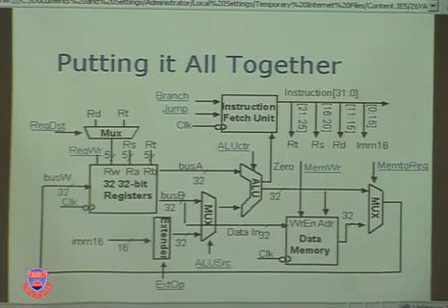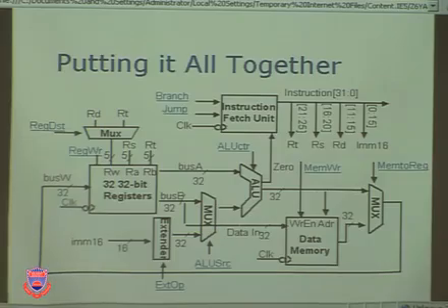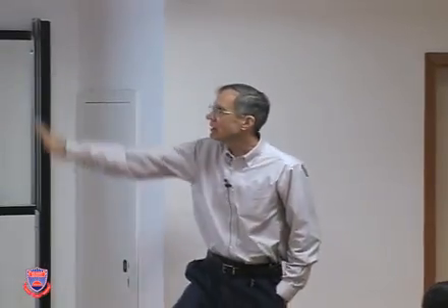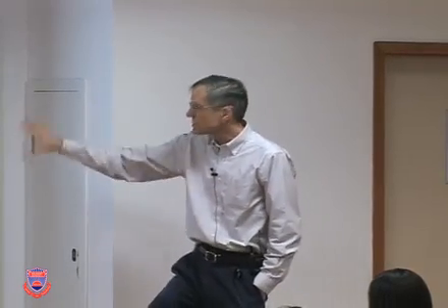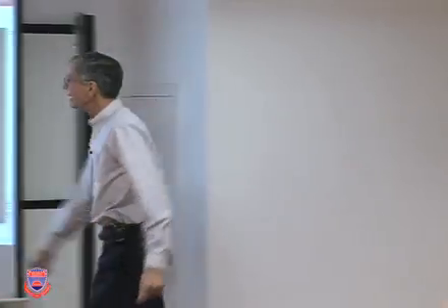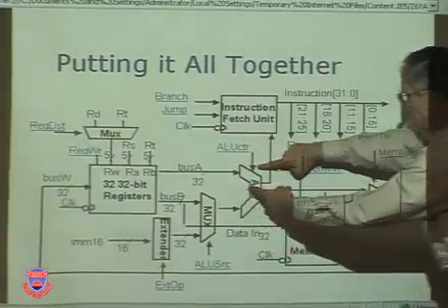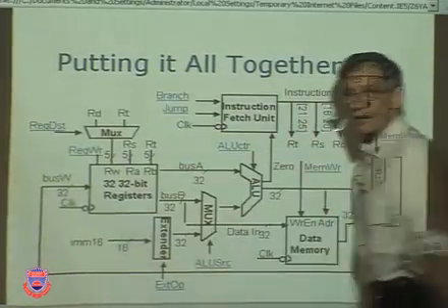Therefore, a box around the whole thing says that's a fancy sequential circuit. It has state. In fact, it's got a few states. It has state. And we haven't even got to the control unit yet. This is still the data path. Yeah, okay. So the data path has state, but its state is register values. Okay? We certainly have to have clocking for this. So you can see why register transfer language is such a perfect language to express what we want to do here. I want to take a couple things here, do something with them here, and stick them here or stick them back here.